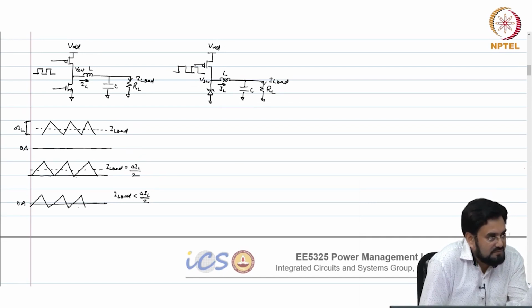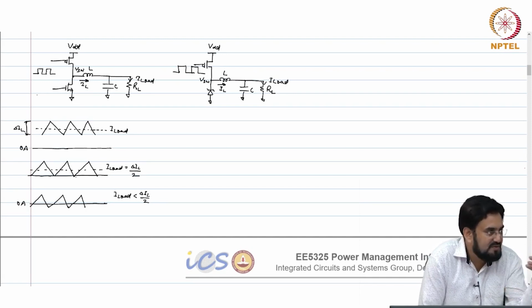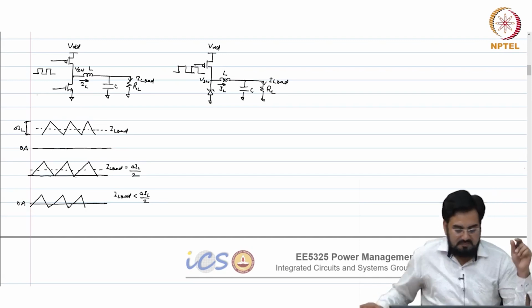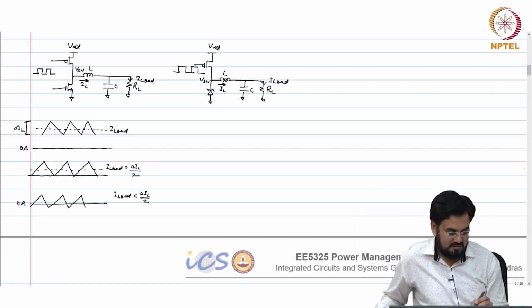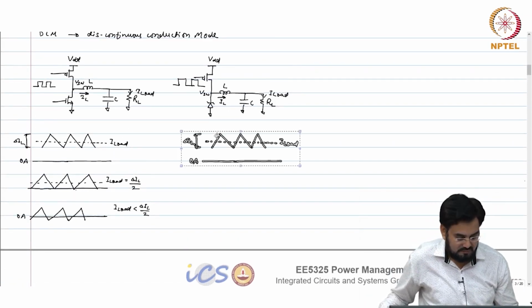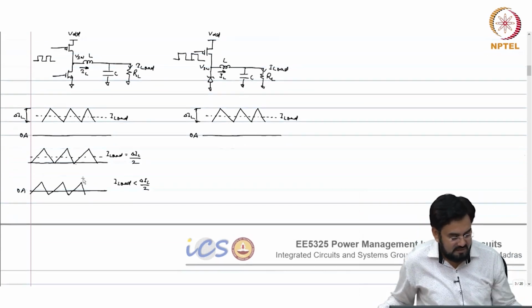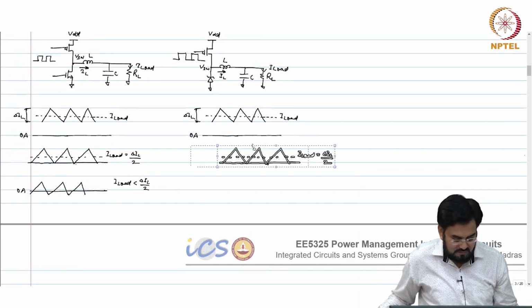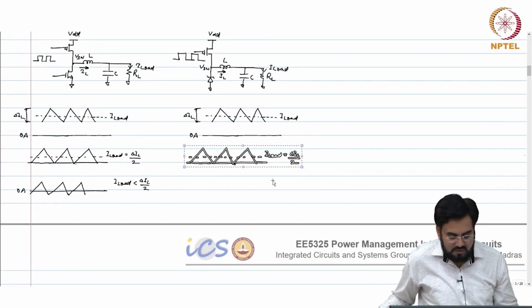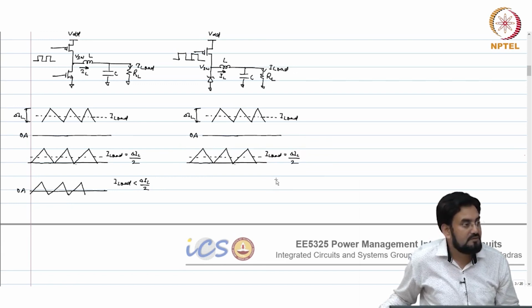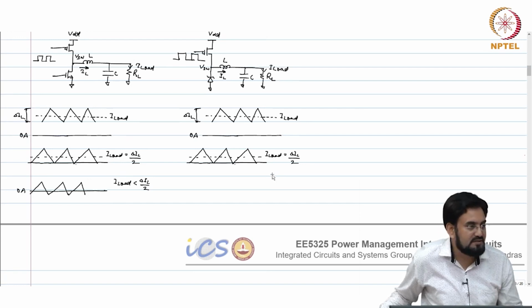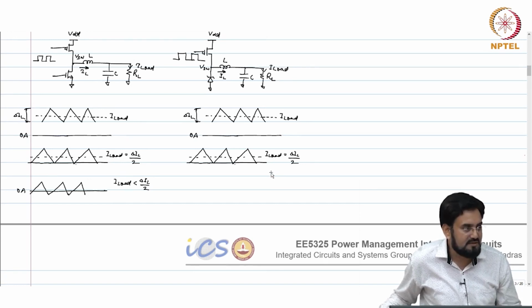So it will work for both negative and positive load current, even at a 0 load current. Okay, because this bottom switch will take care of that. But what would happen here? So this case is fine, straightforward. What would happen in this case? So, this is also okay. Okay, diode is not reverse biased, huh? So, this should be okay, huh?